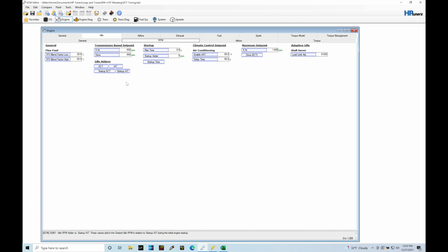Now, we're not actually working in units of torque for idle control, we're working in just the units of RPM. So we want to idle at X RPM, but by telling the PCM that we want to idle at X RPM, we're essentially manipulating the engine's torque to reach that desired idle speed. Every engine will be different in terms of the torque output that it needs to hit a desired idle speed. We can utilize a couple different ways of the engine's combustion in order to get to that desired torque, in order to be at that desired target idle RPM with our idle conditions.